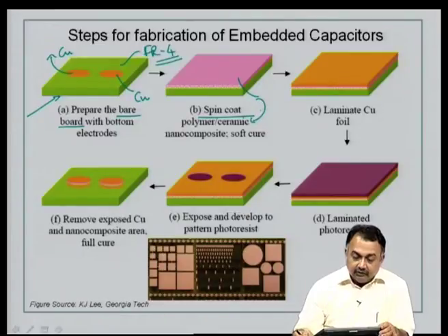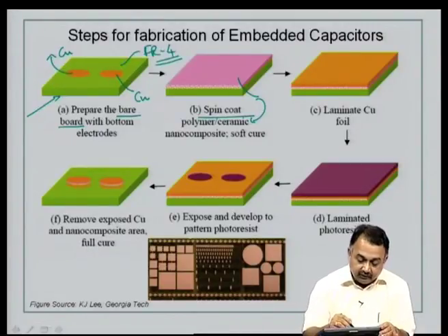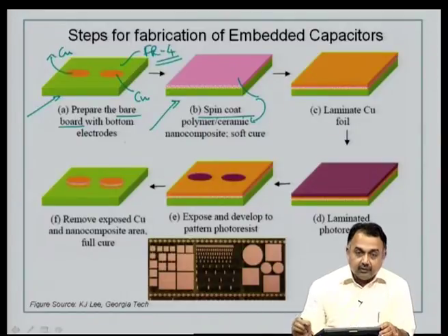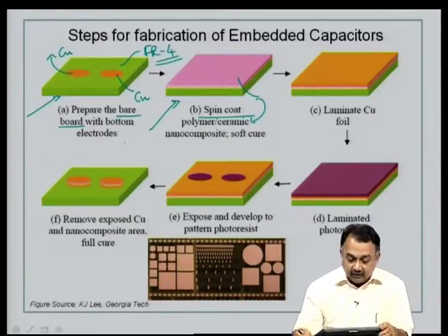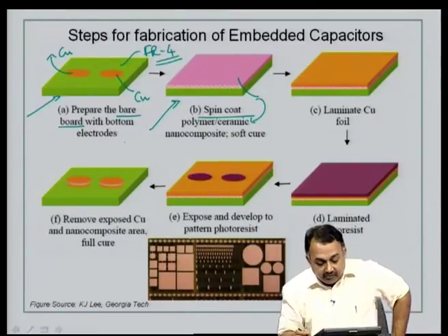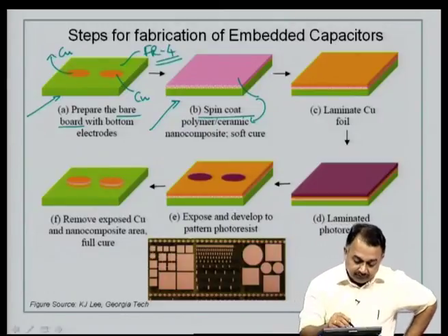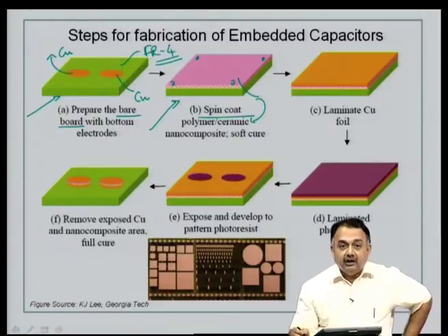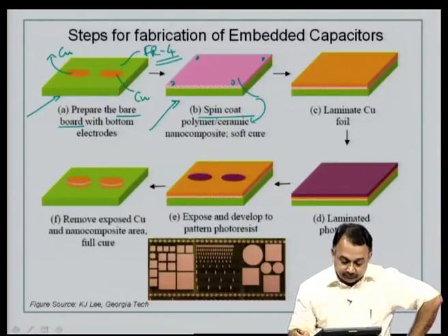Okay. So, there should be good flow, it should be easily used in methods like spin coating, and I want to emphasize here that spin coating for areas like 12 inches by 12 inches seems very ideal, okay, and you can get a very uniform thickness. So, thickness at this stage is very important. If you talk about different areas on the board, you would like to have equal thicknesses on the board.